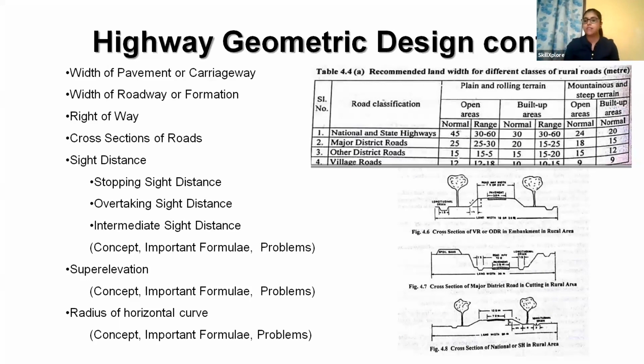Then emotion means there might be some emotions such as anger or stress, so the time spent for that. And volition means the time he takes to apply the brake. At that time the vehicle will be traveling at the speed at which it was already traveling. So that is known as lag distance.